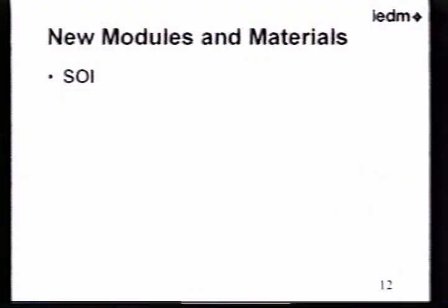So the response to that is going to be a number of different technologies that you'll hear talked about over the next several presentations. One of those, for example, is SOI. Instead of building our devices on top of what is, in a relative sense, a very large substrate silicon region, we can build those on top of insulators. So we can control the depth to which we are getting conduction and flow of electrons and so forth in the bulk, and how that is affected.